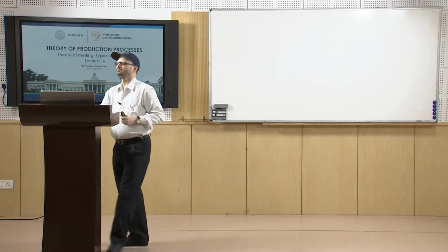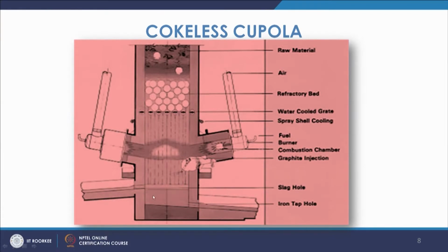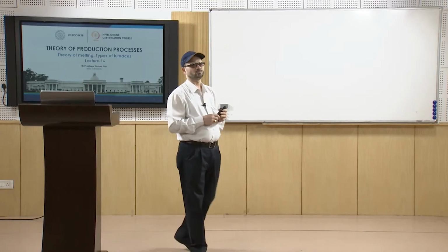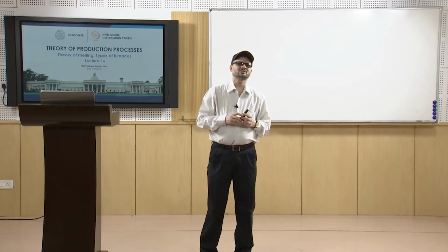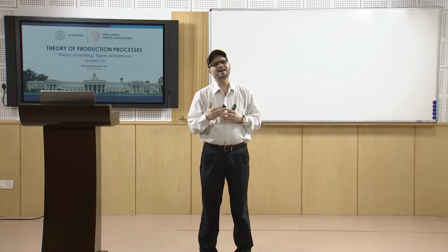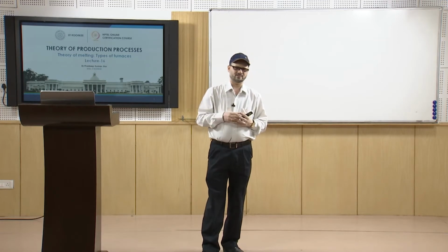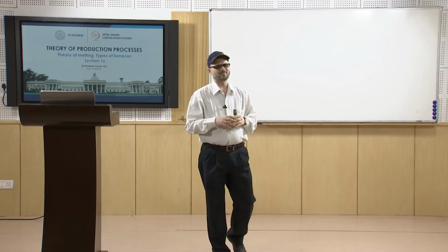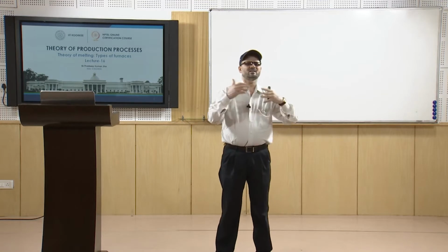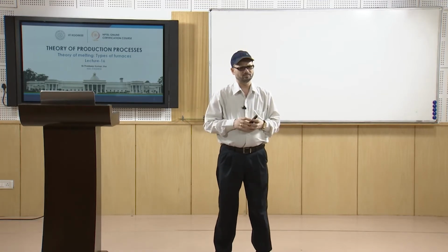As we see further, in this case you will have again the cupola. Now, this is the refractory bed, and this is the case of the cokeless cupola. What happened is that, due to environmental concerns, because cupolas use coke and coke contains sulfur, many times there are gases coming out which are harmful.